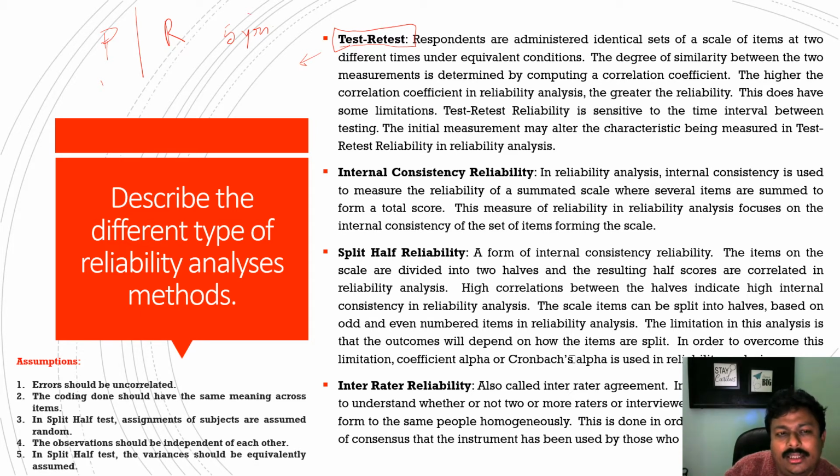So how to identify that the relationship doesn't change within these 5 years? For that, we calculate the correlation coefficient or R square between the data of precipitation and runoff for 5 years. Now the limitation of this system is that it may happen that after 5 years, this relationship may change. Even if for 5 years this test-retest method shows that the data of precipitation and runoff is reliable, if we consider 6 years instead of 5 years, then this relationship may change. So that is an inconsistency of the test-retest method.